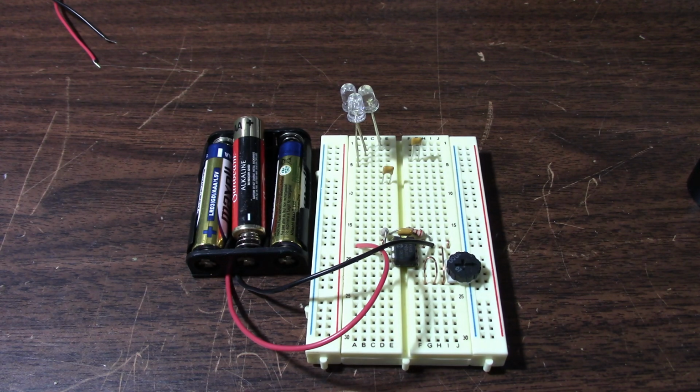That's true. But I think if you really want to flesh out any problems with the amplifier, you want to feed it a signal with a very fast edge, because in the real world, an amplifier with several stages, doesn't matter what type of amplifier, it's a tube amp or solid state, for example, there's going to be some delay in the amplifier response, and the amplifier might show issues with the waveform that has fast rising or falling edges.